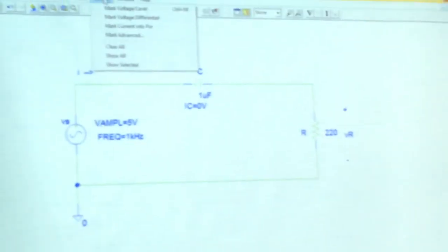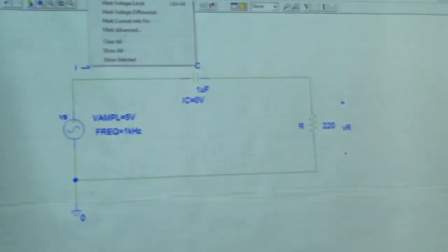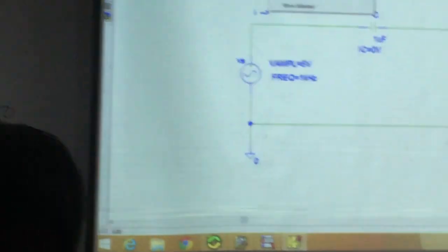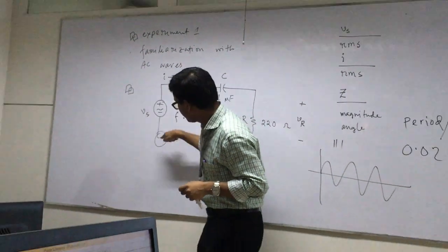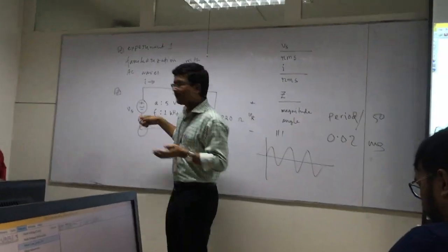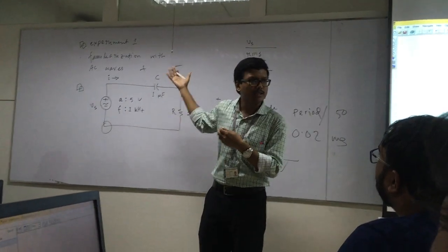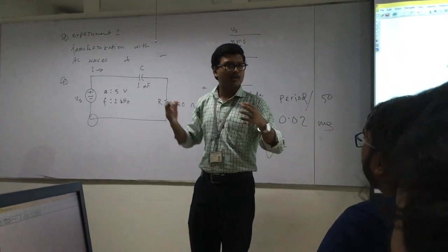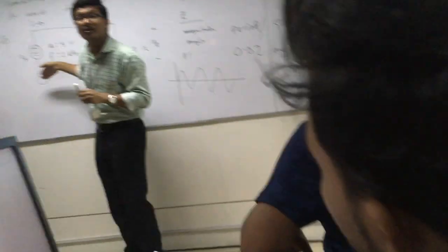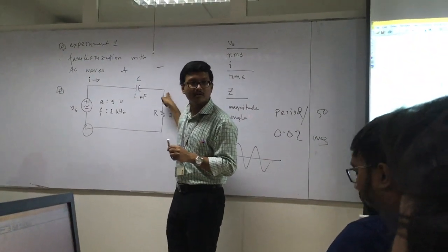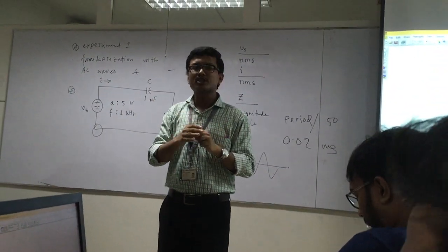So if I say something like this, okay, nodal voltage of this node, there's a meaning. You did nodal analysis. There's a meaning. What do we mean by nodal voltage of this node? We mean the voltage of this node with respect to ground. That's it. That's the meaning. Okay? But what about this guy? Let's say here. It's also a voltage. Is it a nodal voltage? No. Because nodal voltage needs the ground. For example, this guy needs the help of a ground. With respect to ground. With respect to what? Is that ground? No ground. So this is just a voltage, not a nodal voltage. Some voltage, but not a nodal voltage.